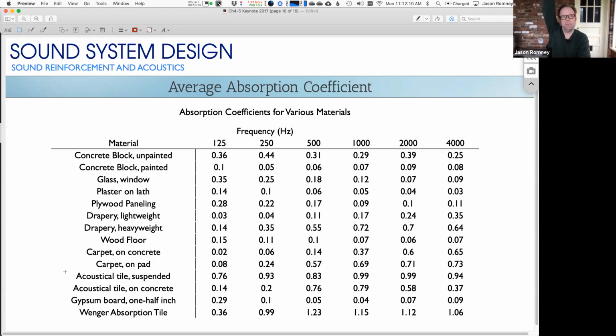And then it travels up, hits the concrete, comes back, and in that round trip, it's gotten quieter, right? Because of inverse square law. And then it goes through the tile again and gets absorbed a second time. So you get a lot more bang for your buck if you can give yourself an air gap between things. This is true of curtains or anything that you would put on a wall to try to absorb sound. If you can put some air between the wall and the thing that's absorbing, it's always going to absorb better. The other thing you might notice is that it's much easier to absorb high frequencies than low frequencies, isn't it?